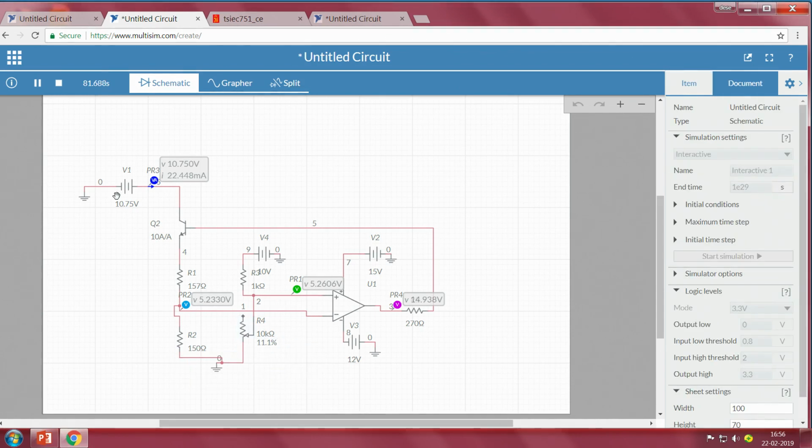Now I am driving the voltage. Now what is it at 30 degrees Celsius? We are talking about a constant temperature circuit. So you want your device here to be maintained always at 150 degrees Celsius. That means the resistance should always be maintained at 150 ohm irrespective of the change in room temperature.